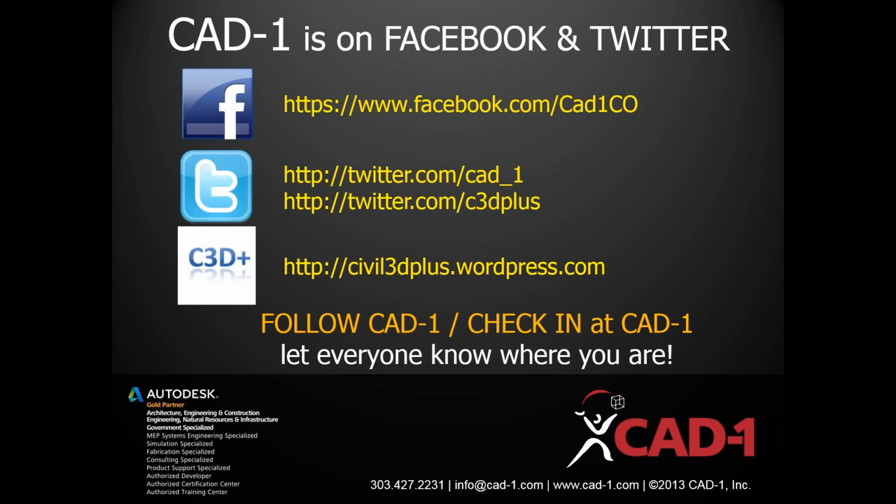Try one thing at a time. Try a text style, make it annotative, plug in your text, see how it acts. Don't try to do it all at once. Pick one thing at a time, get used to it, and then migrate all of those ideas over to things like dimensions and then hatching, etc. Try it out. But before too long, once you get this set up and plugged into a template, I can guarantee you're probably not going to want to go back.